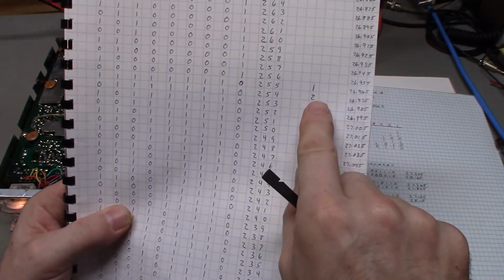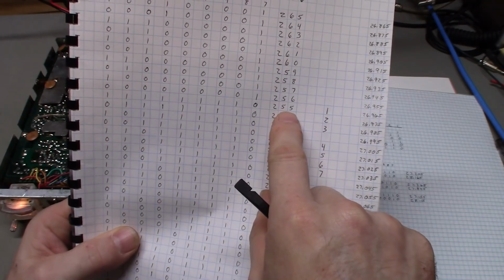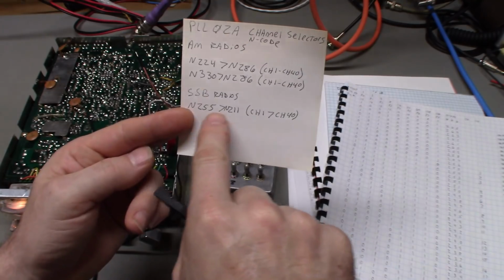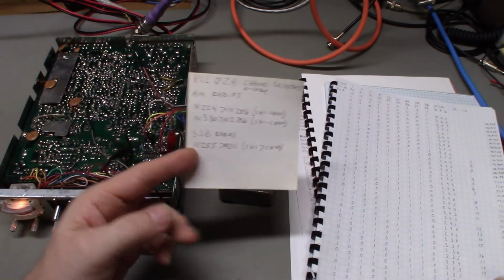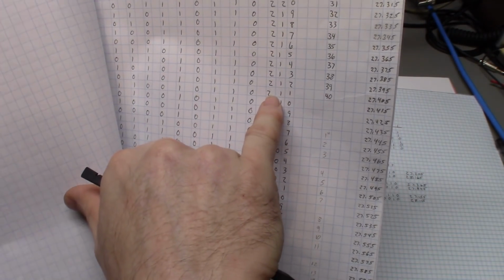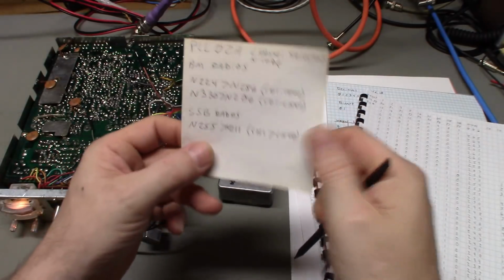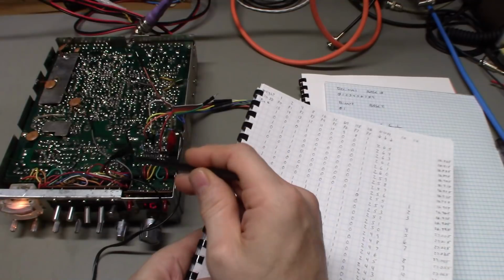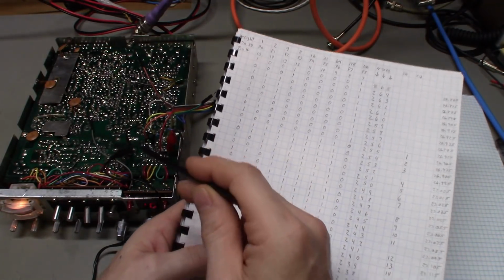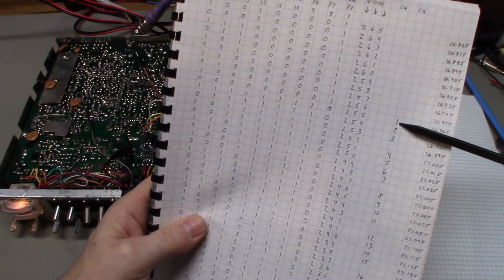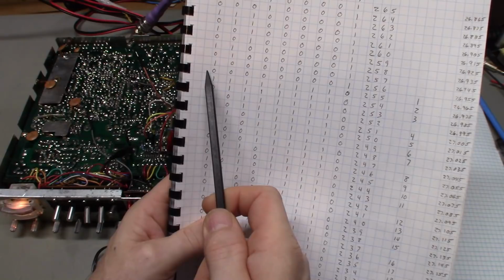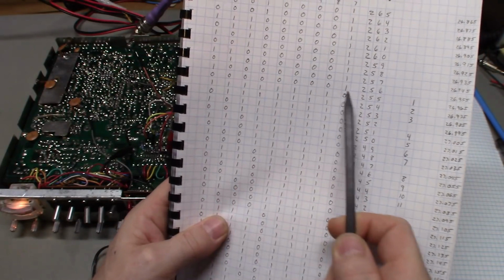And then in the sideband radios, like this one, remember, if we look at the chart here, channel 1 has a decimal or encode of 255, which is exactly what this one has. And if you look up to channel 40, it's 211. Again, if we grab the book here and we look, channel 40 is 211. If you wanted to do a channel modification, remember, getting lower channels out of this radio is going to be hard, because to get channel -1 requires changing the state of every single pin.